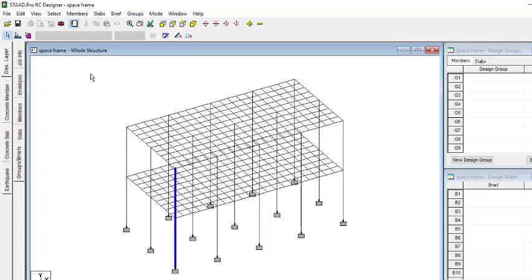And then select this, then you click on member, you say form member, but that will take you a lot of time. Okay, for example, you go to select and you say member. Let me select this. You can see this is a single member. Now select this, it is a single member, select this, it is a single member. Okay, however, this will not even select because it's not a member yet, it is still an element. But that will take me a lot of time when I'm just creating the top and bottom forming member.